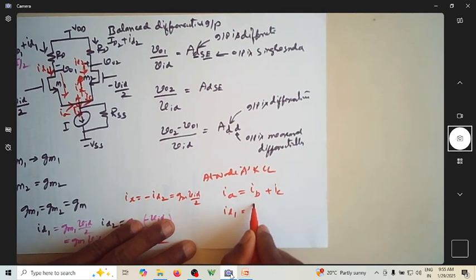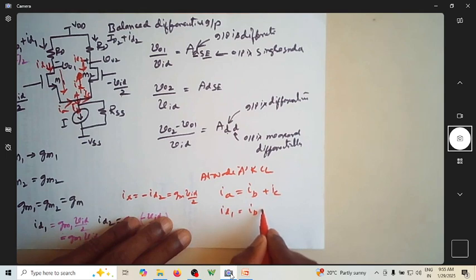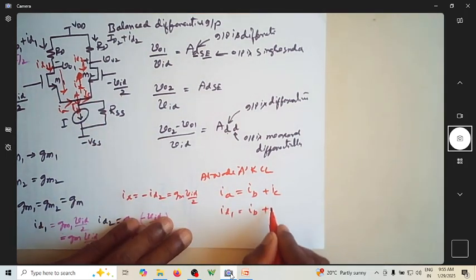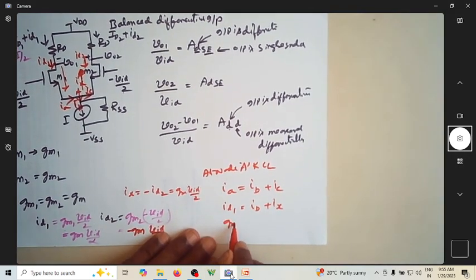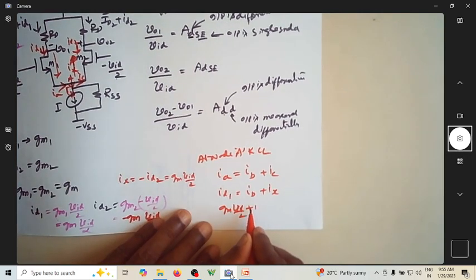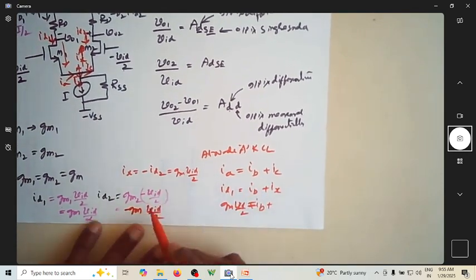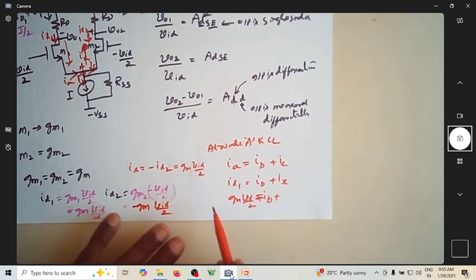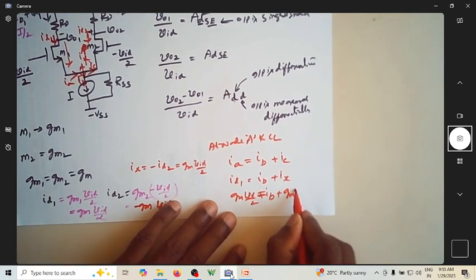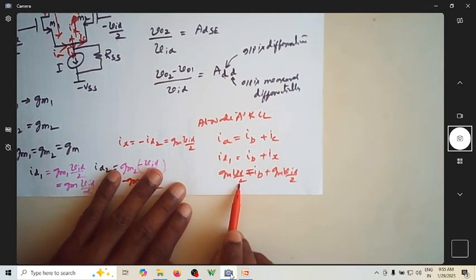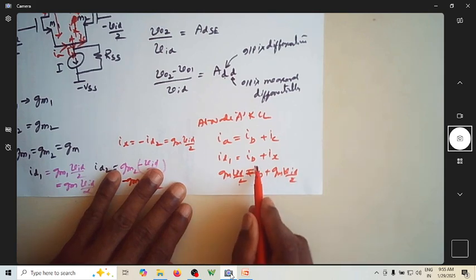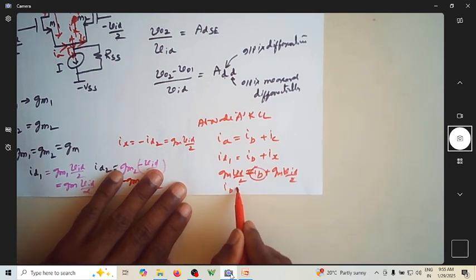I want to know what is IB. So what is IC? IC is actually IX. So IC is IX. So what is ID1? ID1 is GM VID by 2, which equals IB. What is IX? IX is actually minus, this is actually GM into VID by 2. You can see now this is GM into VID by 2. This is also GM into ID by 2. Then what is IB? So IB is actually 0.